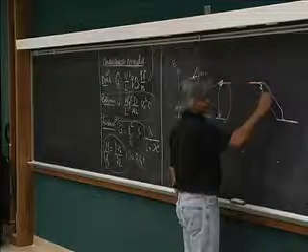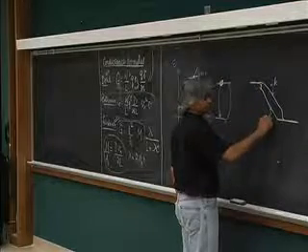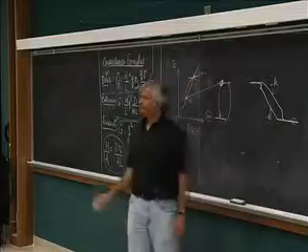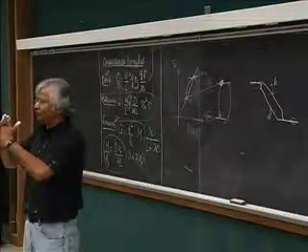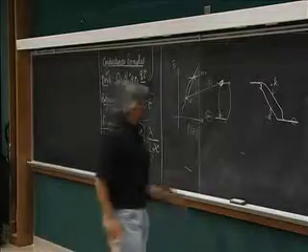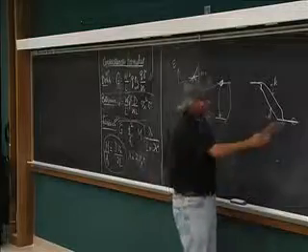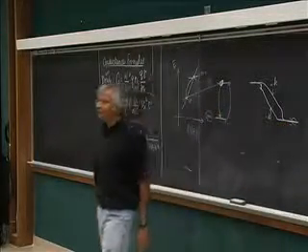where I said there is a certain separation between positive-going states and negative-going states. But once you get into the contact, there is no separation. People say, well, sure, once you get into the contact, it's all in equilibrium. But if you think about it, current is the same everywhere. So if there is no difference between plus and minus, how is the current being carried?